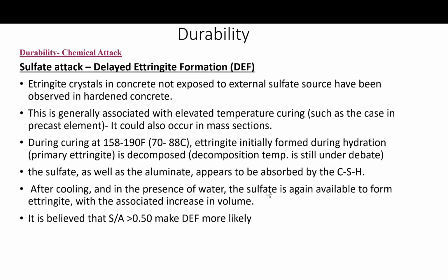We also have ASTM C1012, which is designed to provide a means of evaluating the expected sulfate resistance of concretes and mortars made using Portland cements, blends of Portland cements and pozzolans or slags, or blended hydraulic cements in general.